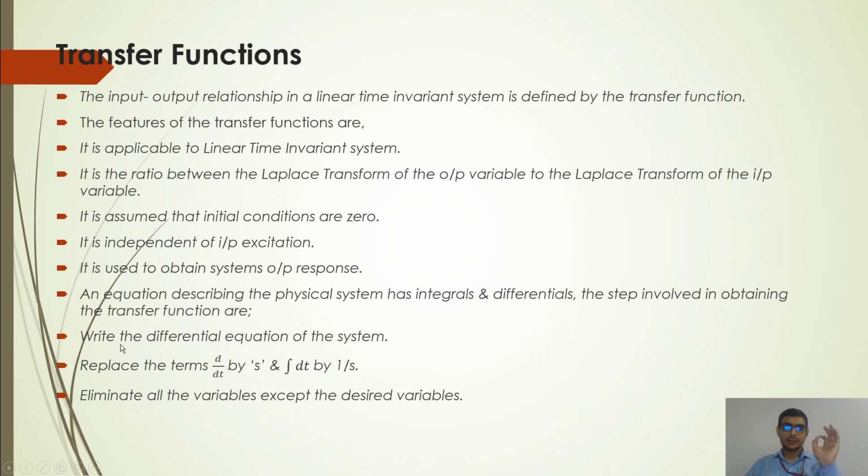The Laplace transform of equations can simply be taken for a simple system by replacing d/dt by s, or integration of dt by 1 upon s. Suppose we replace the equation of the system by these things, the system would be converted into the Laplace domain.